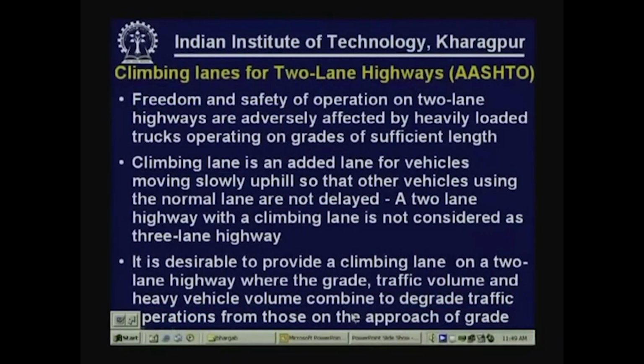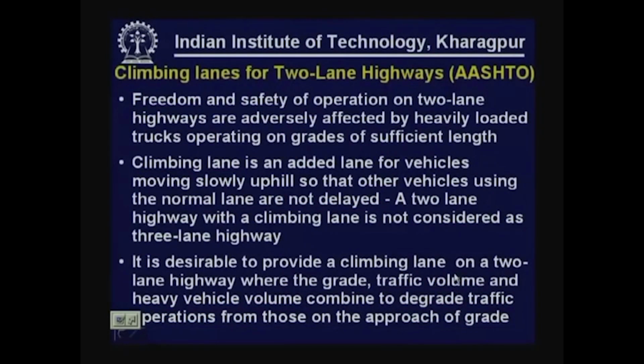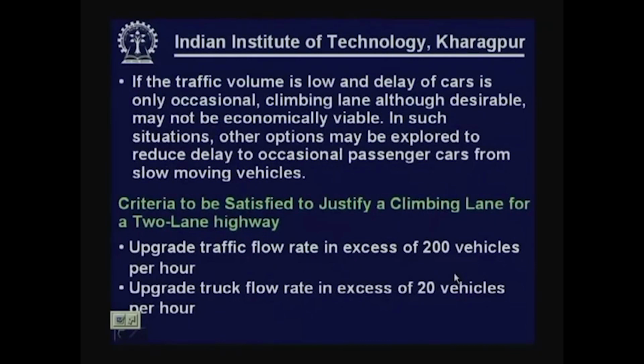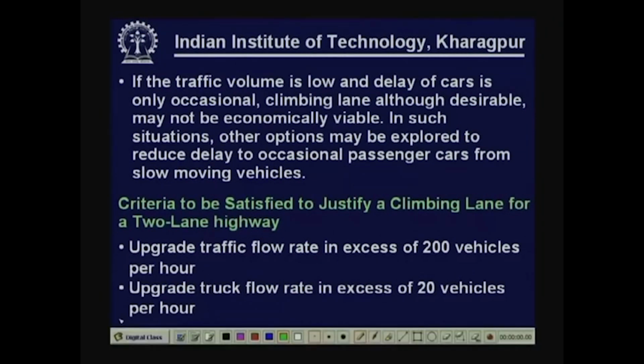Of course, a climbing lane may also be desirable even if the traffic volume is low and delay of cars is only occasional. Carefully observe this part: delay of cars is only occasional. That means overall traffic volume is low, and it is not that all the time a fast moving vehicle is forced to follow a slow moving vehicle, and not that all the time there is a long queue.